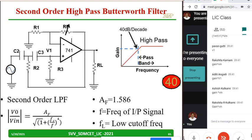In second order, we take R2 equal to R3 equal to R, C2 equal to C3 equal to C. These are some of the points you have to remember. In case of first order, 20 dB. In case of second order, it is 40 dB per decade. Hope most of you have copied this.